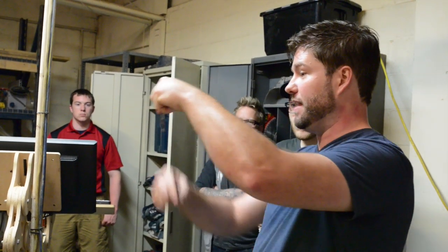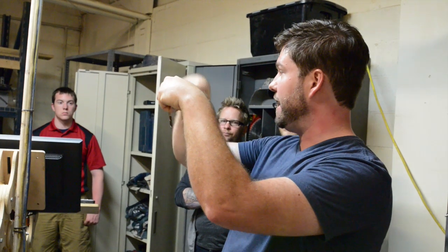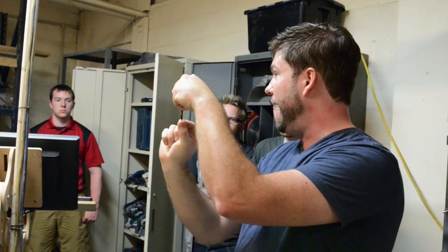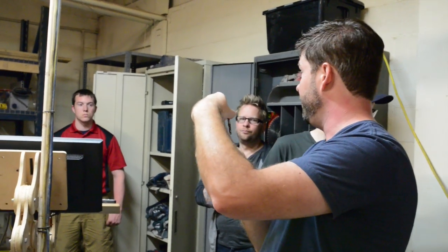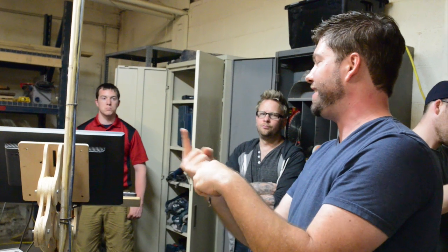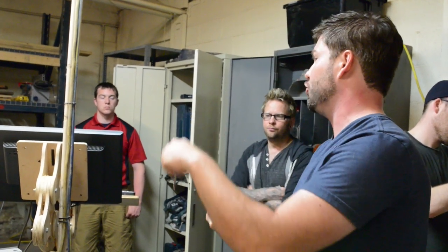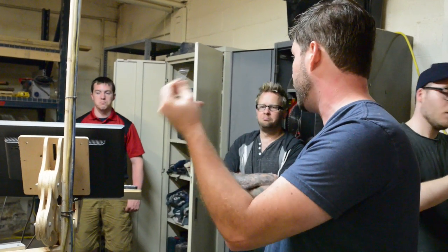The spirals on top force the wood chips to stay down. The spiral changes at the bottom, which forces all the sawdust to stay in the cut, and the sawdust holds the piece in there. You can do a 6-inch circle all the way through without a hold down, and the piece will not pop. So I highly recommend these bits.